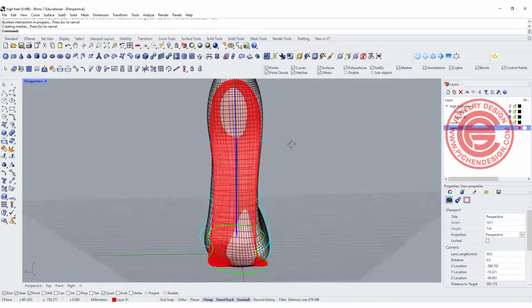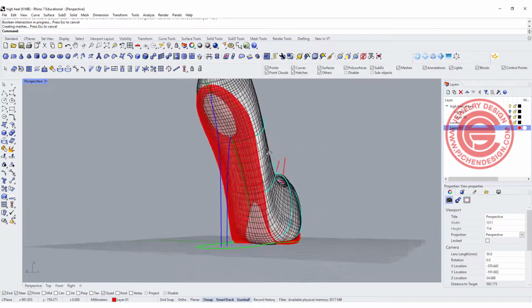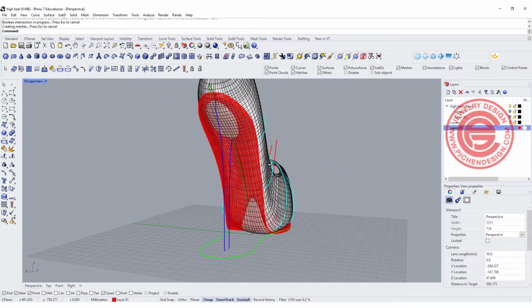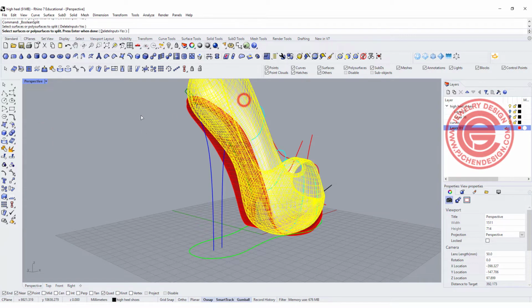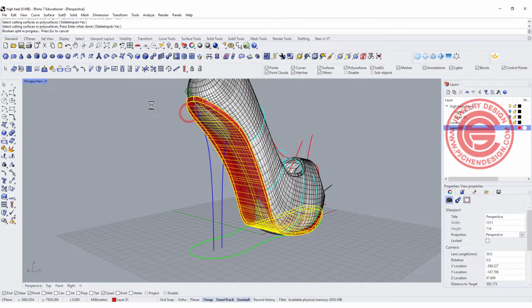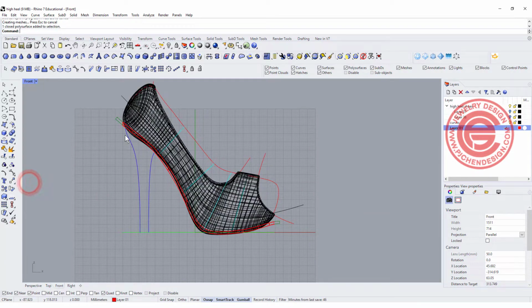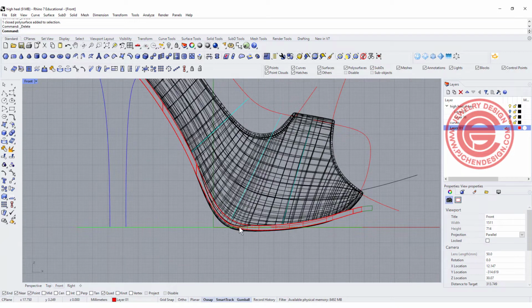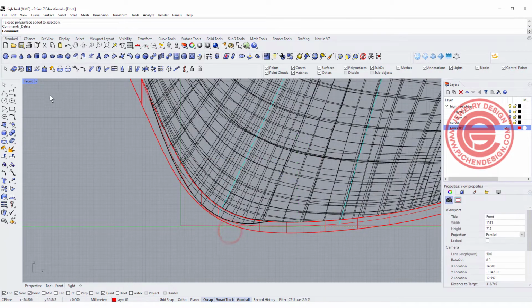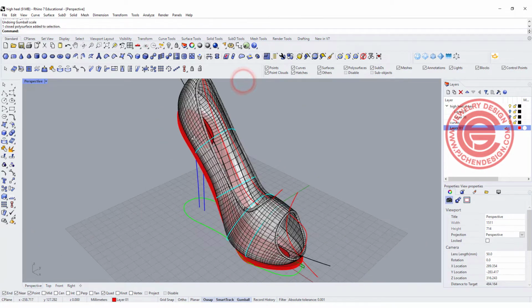Once you find the shape that is fitting into it and covers the area you want to cover, what you want to do is use the Boolean Split, and you want to pick up this one and split by this one. So you can delete the extra here, here, and also the one on the bottom, and keep tweaking until you find something that you like.